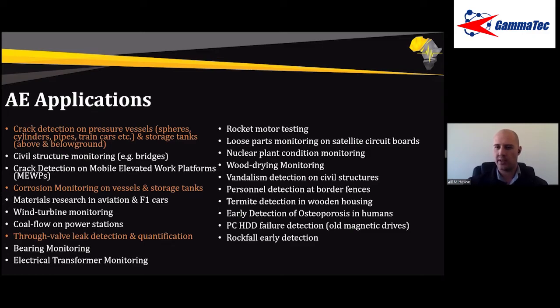Okay, here we have a question for corrosion under insulation on piping. Acoustic emission is quite effective for corrosion under insulation on piping. We would just need to cut out holes in the insulation, attach the sensors directly to the piping, and then monitor. Now, here there are various limitations.